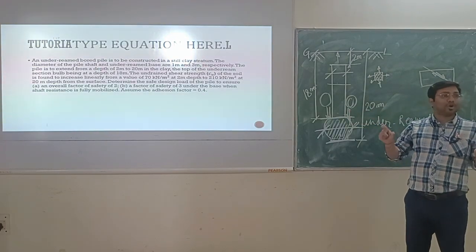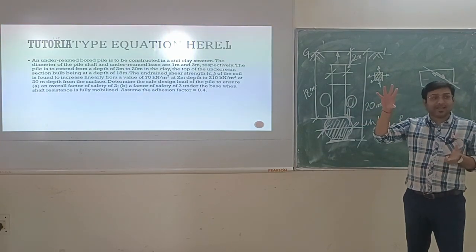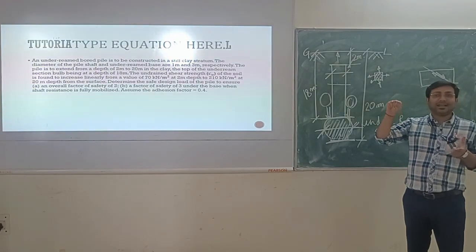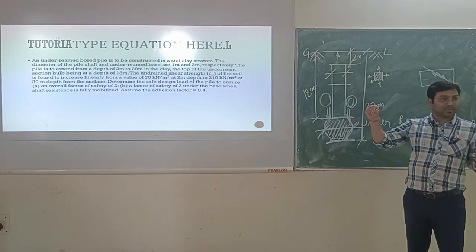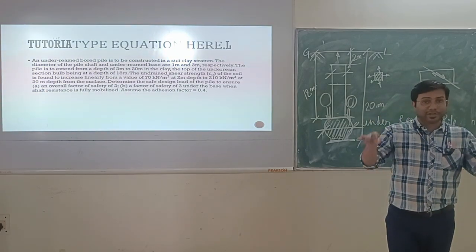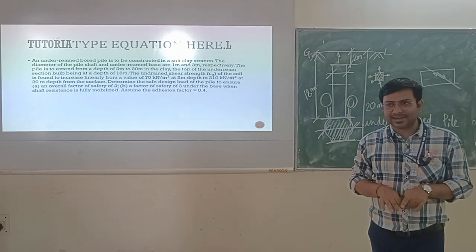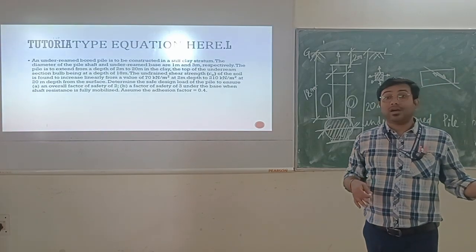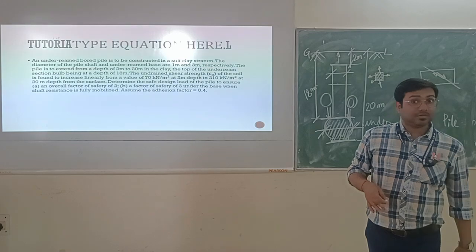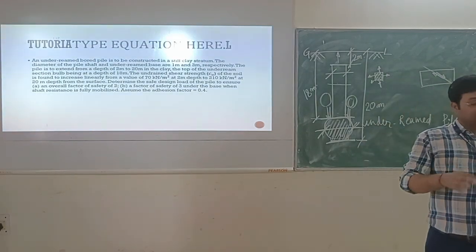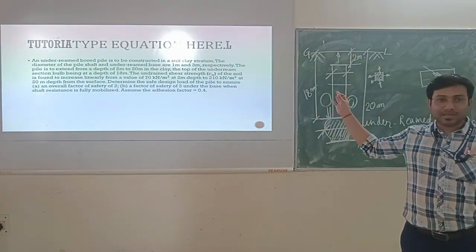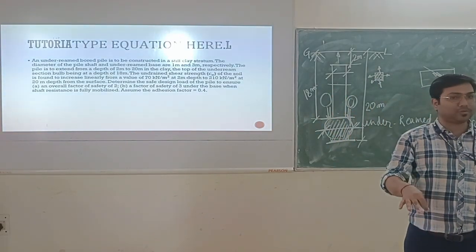If that is not happening after squeezing, after giving external pressure, water cannot come out from the soil pores. That is called undrained condition. Now, this is the technical or theoretical definition of drained and undrained condition. But why are these kinds of conditions appearing? No, this is not related to pile foundation or advanced soil mechanics. This is the basics of soil mechanics.